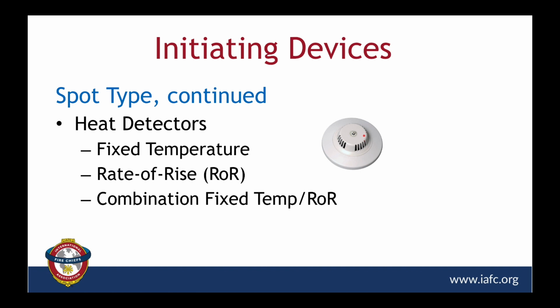These respond to thermal energy, obviously heat, and they activate when the detecting element reaches either a predetermined fixed temperature or when a specified rate of temperature rise occurs. Looking at fixed temperature detectors, they activate when the sensing element becomes heated to a predetermined level, typically 135 degrees Fahrenheit or 194 degrees Fahrenheit.